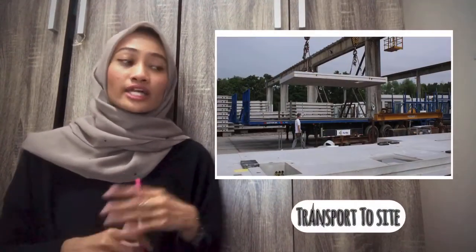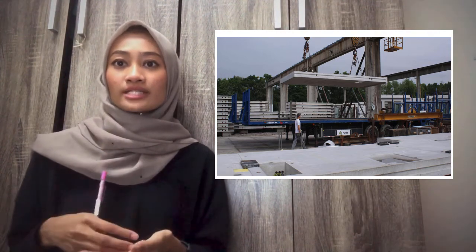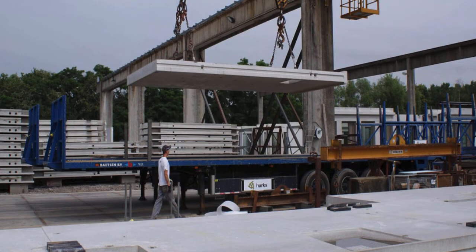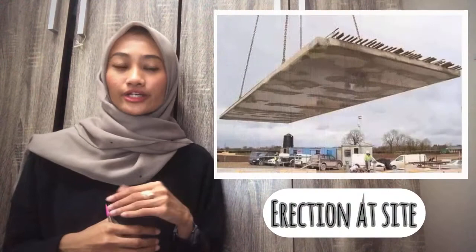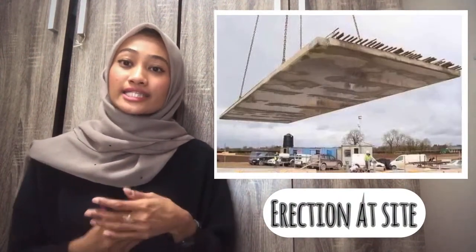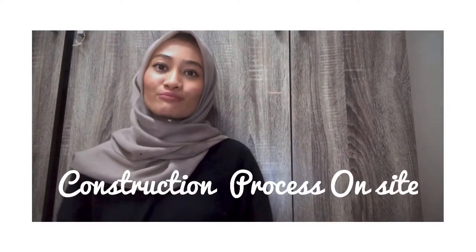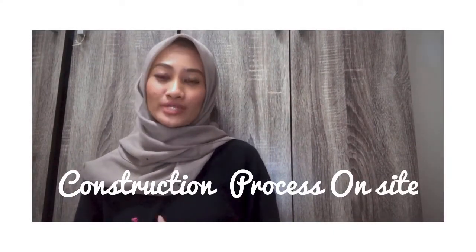The components are delivered to site in a predetermined sequence to ensure the hardened concrete is ready for immediate erection. This figure shows how the components are delivered. Then after that, erection at site. The components are erected straight from the lorry. This leads to faster erection times with reduced on-site activity. Next we move to the construction process of precast concrete framing on site.